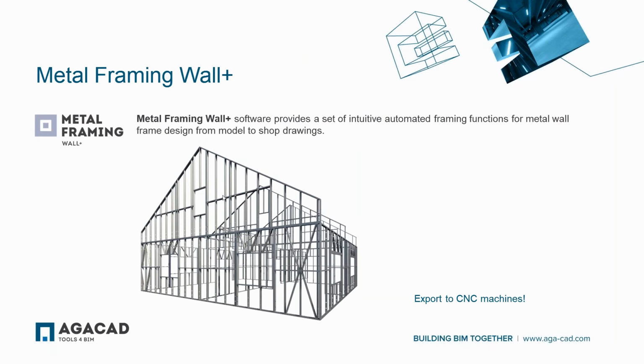Now in our metal framing suite we have Metal Framing Wall Plus, which is for framing walls which come from Architect. With this tool you can predefine your own configurations and you can frame the walls easily. At the same time you can make shop drawings.